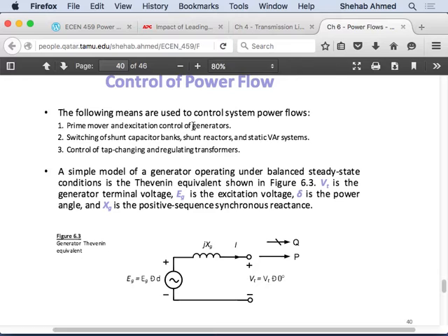It's really important. Any generator has two main control circuits. One control circuit controls the field winding current, which is basically a control of the back EMF voltage that's induced across the turns, which is indirectly controlling reactive power in the system. So this is the way you would control reactive power in the system, by controlling the excitation of the generator. And we'll draw the phasor diagram for a simple equivalent circuit like that.